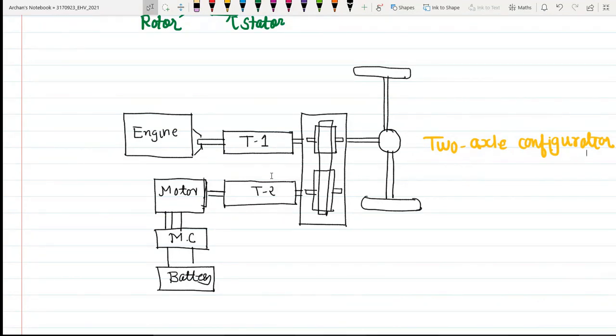So in an actual hybrid drivetrain, the maximum tractive effort with this transmission arrangement may be sufficient for the hill climbing performance of the vehicle. Okay, greater tractive effort would not be necessary due to the limitation of the tire-ground contact adhesion. You can see. Okay, the use of this single gear transmission takes inherent advantage of the high torque characteristics of electric machines at very low speeds. Okay, and talking about the second, the multi-gear transmission.